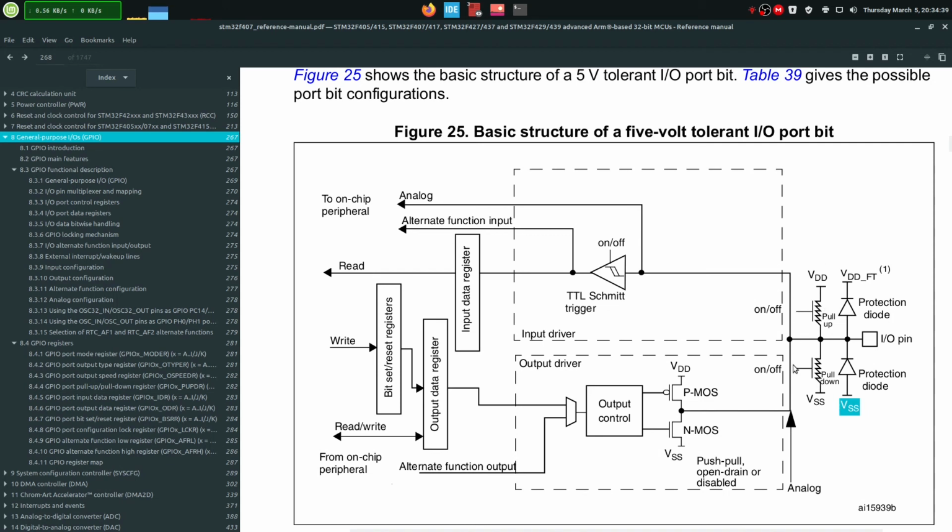Here we can see the pull-up and pull-down resistors, very useful, although if you have some kind of buttons, which we're going to talk about later, it's always good practice to introduce external resistors for prototyping, measuring and stuff like that. But if you don't have space, and if the boss really doesn't like you and is really counting every penny, you have internal pull-up and pull-down resistors. You have full control of this. And this is the smart part of the input. So this is the input part and this is the output part.